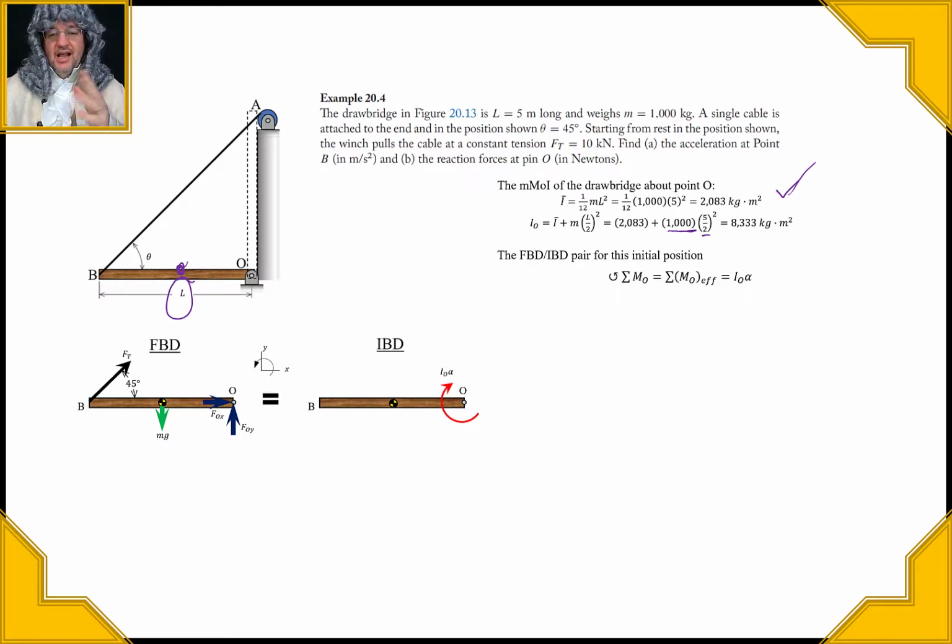We don't need to double down on here. Now, when it comes to my reactions, I might want to put them on there, but I want to leave it for now without putting mass times acceleration on there, because you don't want to double dip. That's one of the reasons for the previous explanation about using the parallel axis theorem and how that's built in. We don't want to double dip and also include the effective inertial moments when we've already taken care of them by taking the parallel axis theorem and shifting the thing out.